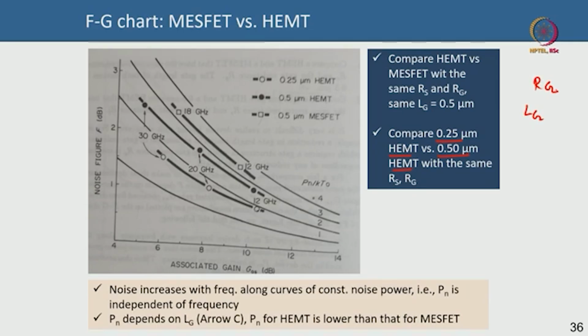That is why in this particular study the authors have maintained the same gate resistance by using a mushroom gate or whatever is needed, so that the gate resistance is the same, although the gate length is different. You can use a mushroom gate. They also have maintained the same source resistance by device engineering. Same source resistance, same gate resistance, so that the effect is identical.